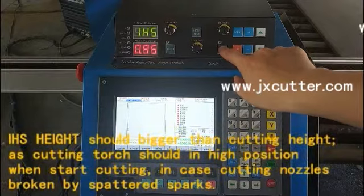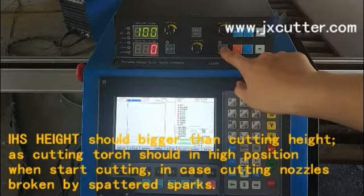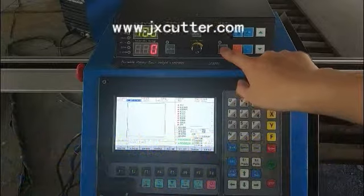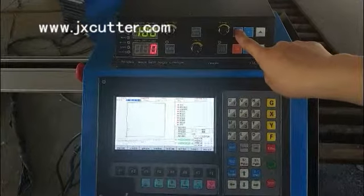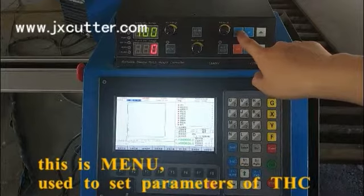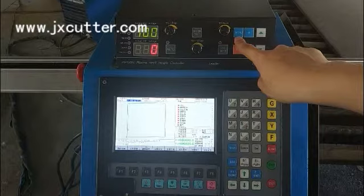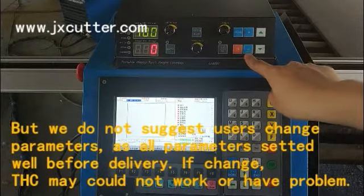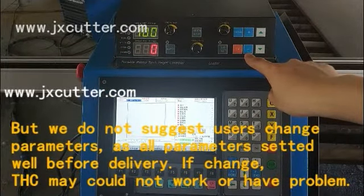IHS height should be bigger than cutting height, as the cutting torch should be in a high position when starting cutting, in case cutting nozzles are broken by spattered sparks. This is the menu used to set parameters of THC. But we do not suggest users change parameters, as all parameters are set well before delivery. If changed, THC may not work or have problems.